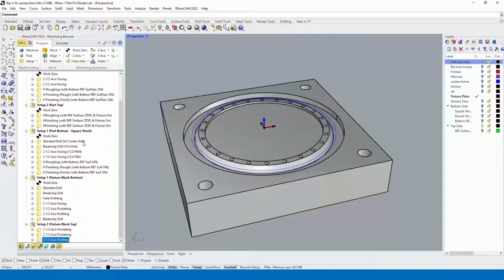And this is relatively complex, but they can get more complex than this depending on the part geometry. So the main thing to remember on each of these types, if at all possible, make sure your part and your stock are aligned in the center in relation to each other, regardless of where you're setting it, where the work zero is, or where it's going to be on the machine.